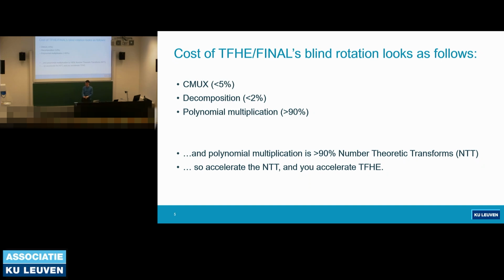And so that requires some analysis, because that requires knowing what you are trying to build. And in our case, we are doing TFHE computations. The output of our factory, of our FPGA, is blind rotations, effectively, because that's the main part of a TFHE. If you get the blind rotation right, all the rest you can handle in the CPU and some more custom thing. Your FPGA should really be built for the blind rotation.